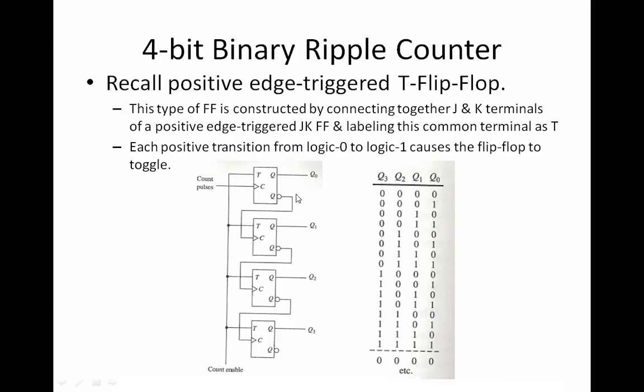In the next step, when this becomes 0, then 1 is here, so this is enabled. Whatever was there previously, which was 1, gets passed to the next flip-flop. So it is waiting for the next clock cycle to pass from one flip-flop to the other.